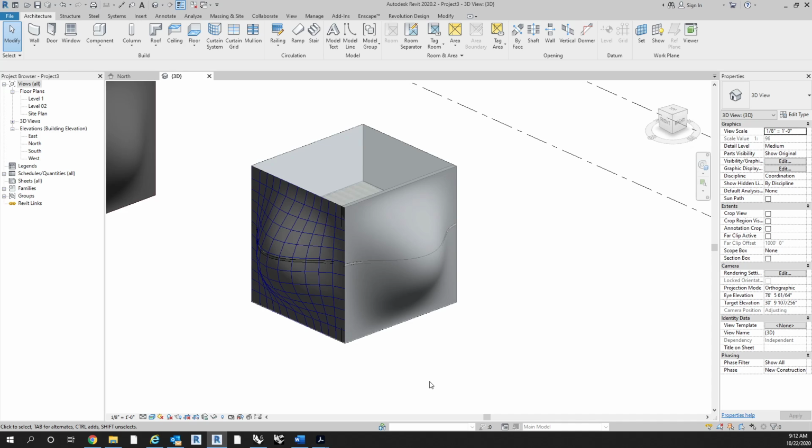If you're developing the geometry in Rhino, I would do tests, right? So as you're developing it, export the geometry and import it in here. Make sure that you can still turn it into a conceptual mass, actually be able to manipulate it, and as you develop it, continue to test, so that you're making sure that what you're doing within Rhino is working, and you can catch any major change that you make that actually errors out.